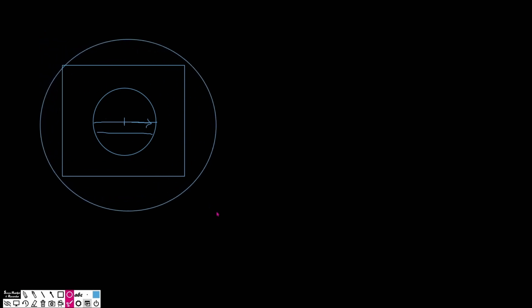Why is this important? Let's imagine that I have this foundation pile, and of course I want my diameters to always be inside of this. If I leave the diameter, or the radius, totally free, the final user of the family can create a foundation diameter that makes no sense.